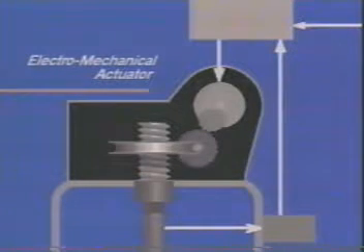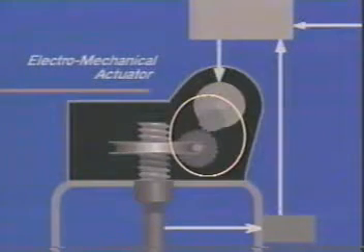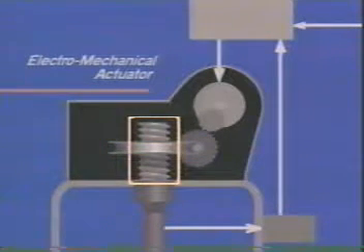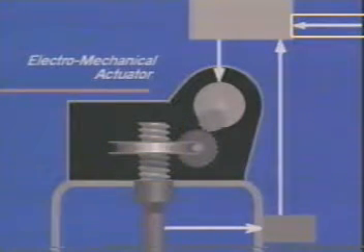One type of actuator that is not affected by these factors is an electromechanical actuator. Essentially, these devices have an electric motor and gear train that actuates the valve. The gear train drives a worm gear, which converts the rotary motion of the gears to linear motion for the valve stem. The magnitude of the control signal sent to the valve corresponds to the desired valve stem position.